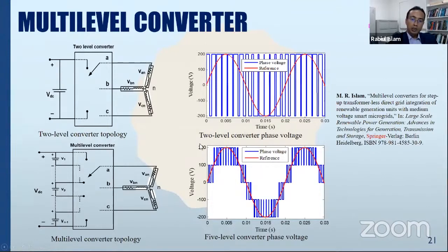On the other hand, with this converter topology, you see a number of voltage levels. Actually, each IGBT or switching device handles only one voltage level, not the total voltage level across a switching device. Therefore, we can use commercially available low voltage rated IGBTs to develop a high voltage inverter or converter. But with the traditional technology, it is very difficult.